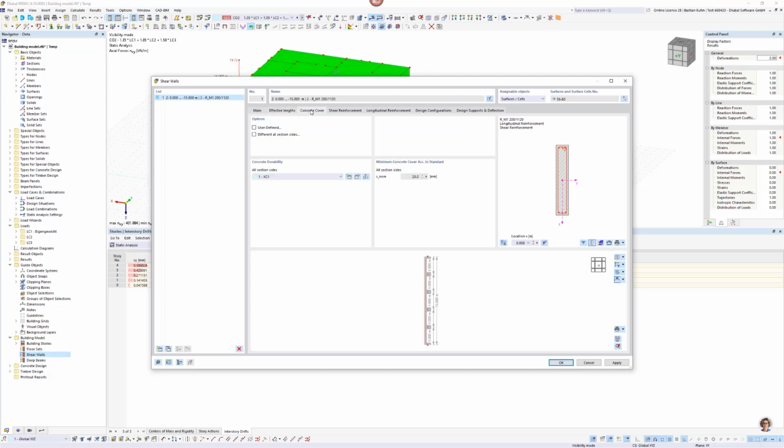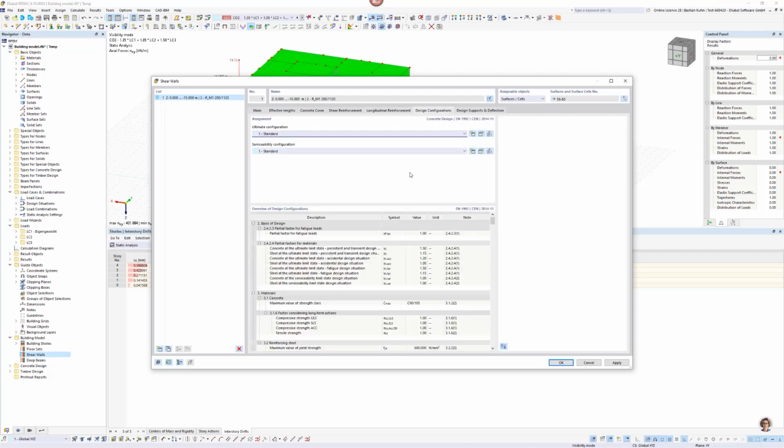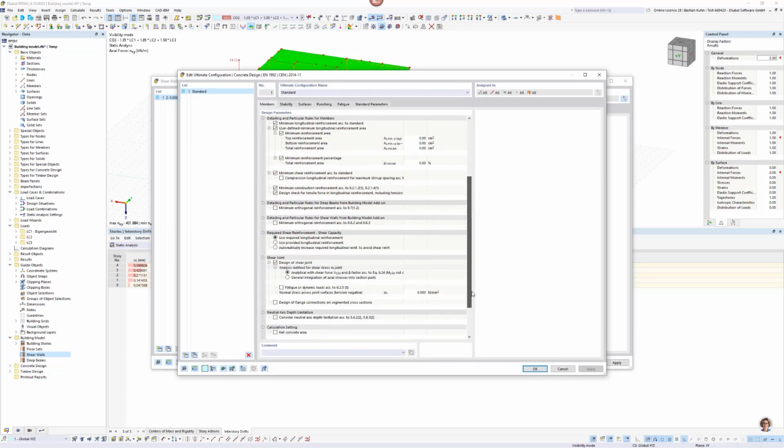do a stability analysis with the concrete add-on in it. I have the covers in here, reinforcement, and so on. But here in design configuration, that's an interesting part I wanted to show you from the building model. It is choosing the deep beams and also the shear walls from the building model add-on. And so the program will automatically put the reinforcement in relation to what is activated in the building model from this wall into this surface that I'm defining here.